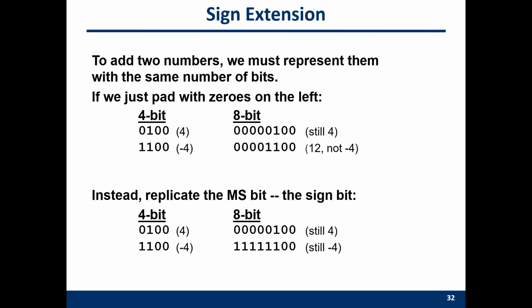However, if this number is negative, and you write all zeros into its most significant bits, these 4 most significant bits, this is not right. Why? Because this number is actually a positive number. The significant bit of this is a 0. So instead of writing all zeros here, you need to write all ones. This is the real negative form. In this number, the most significant bit is 1, so it's a negative number.